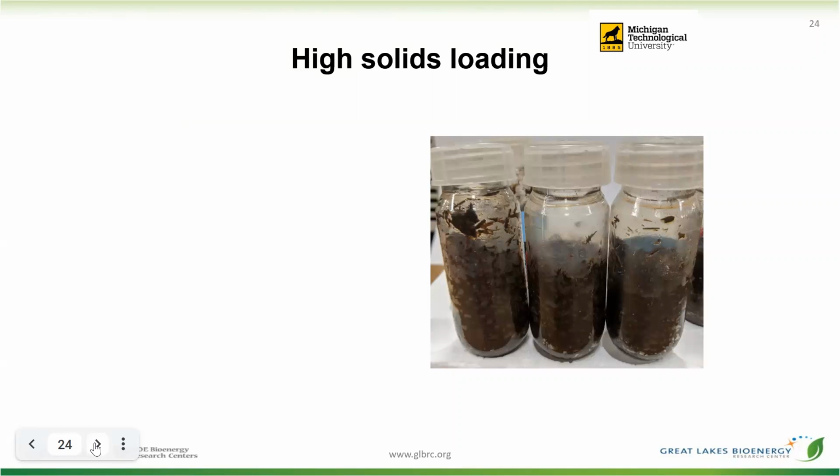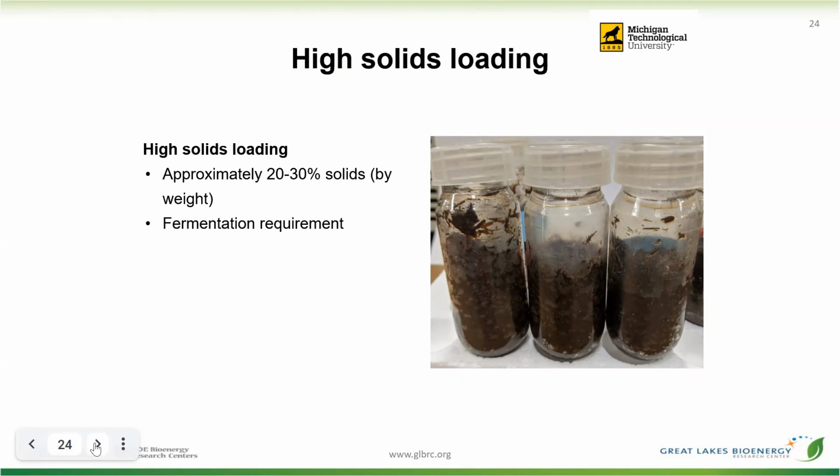High solids loading condition. 20 to 30% solids proportion by weight can be considered as high solids loading in enzymatic hydrolysis. Why do we need such high concentrations? It is because this is the industrial requirement for fermentation experiments.